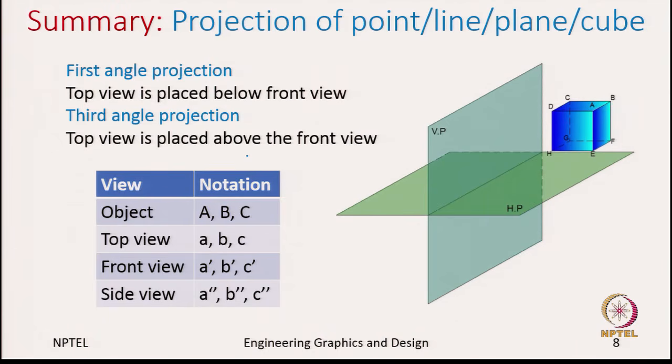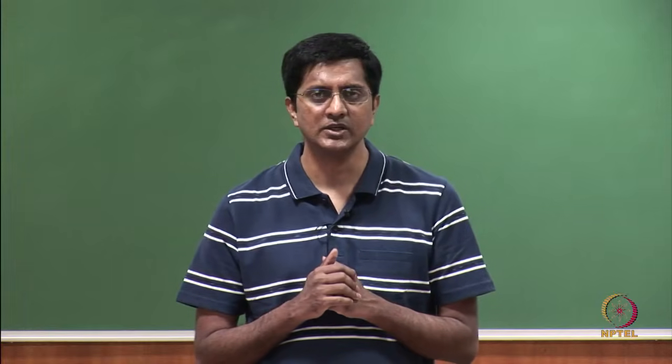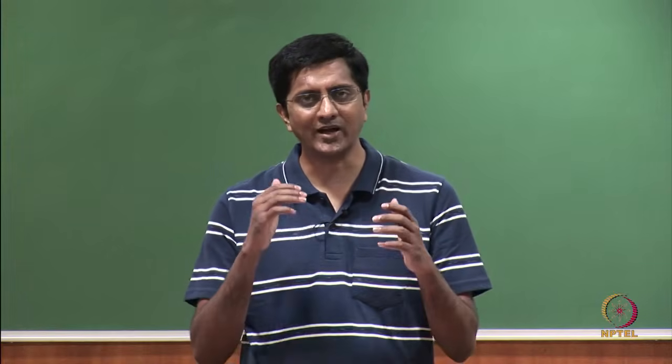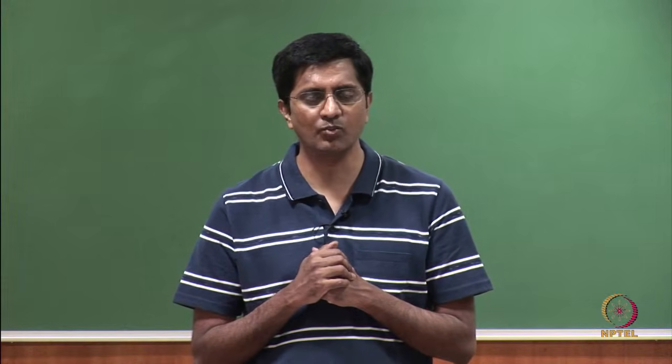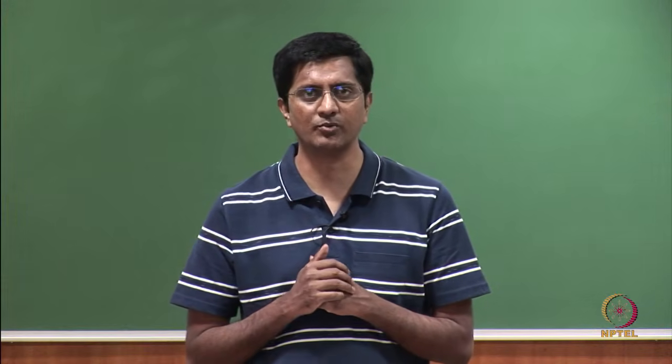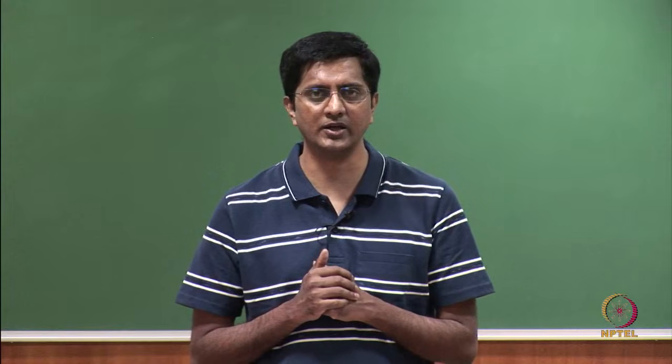So, finally, to summarize, in this lecture what we have learnt is how to project simple things like a point, a line, a plane and a cube. The important thing to remember is, if your feature is parallel to the projection plane, you capture the true view. This is more important when we discussed projection of a line, a plane and a cube.